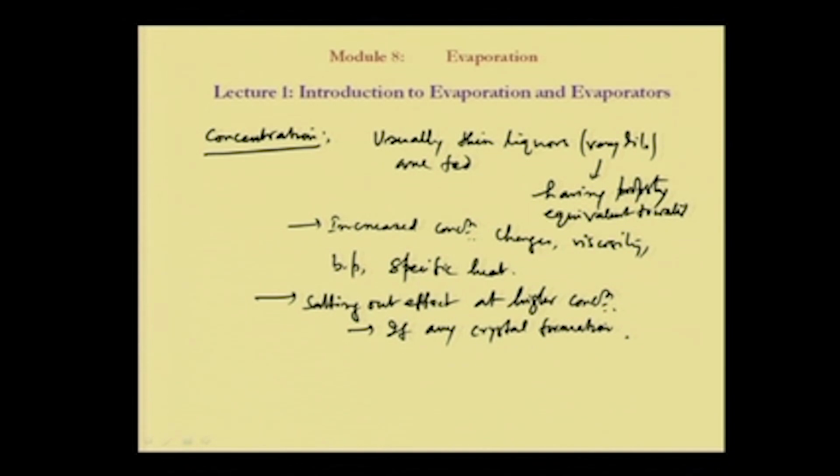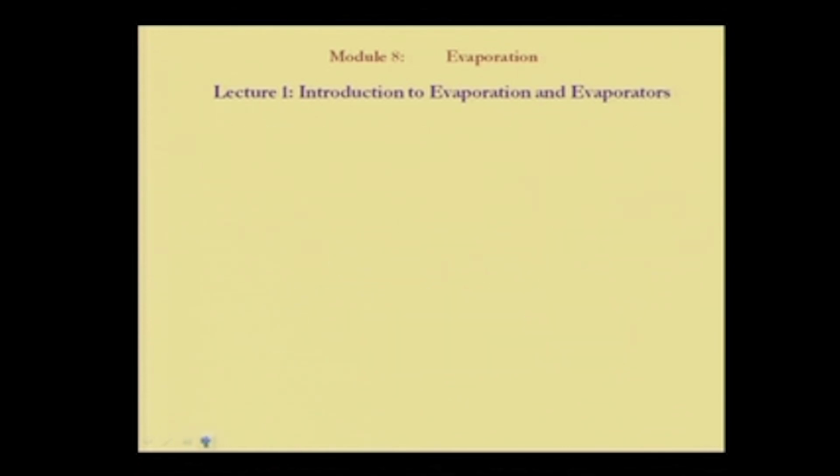We also have to see to what extent the viscosity is increased, whether there is flowability or not, and increased viscosity changes the heat transfer behavior and the heat transfer coefficient. All these things are related to the concentration of the evaporating liquid, and they have to be taken into consideration.